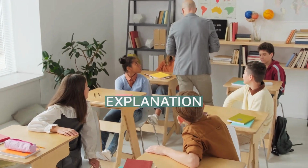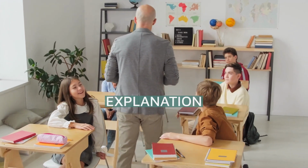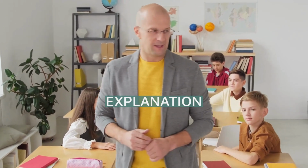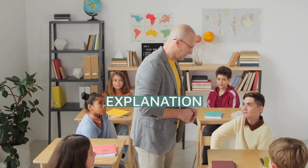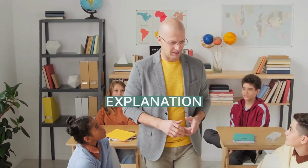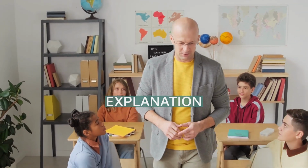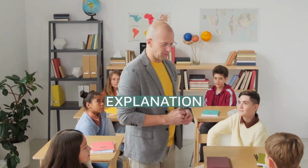Contact angles greater than 90 degrees (high contact angle) generally mean that wetting of the surface is unfavourable, so the fluid will minimise contact with the surface and form a compact liquid droplet. For water, a wettable surface may also be termed hydrophilic and a non-wettable surface hydrophobic. Superhydrophobic surfaces have contact angles greater than 150 degrees, showing almost no contact between the liquid drop and the surface. This is sometimes referred to as the lotus effect.